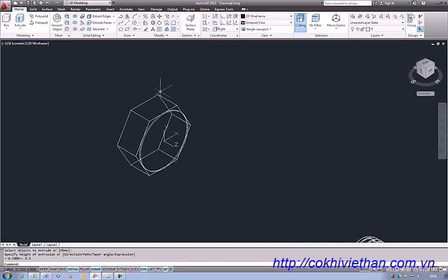All we need to do now is chamfer the back corners of the bolt head here, and the way that we're going to do that is we're going to create another circle on the back of the nuts here, and then we are going to extrude that circle, but extrude it at a taper angle so that it passes through the corner of this bolt head, and then we're going to subtract the volume of that from the body of the bolt head, and it will cut the corners off. So let's start the circle command.